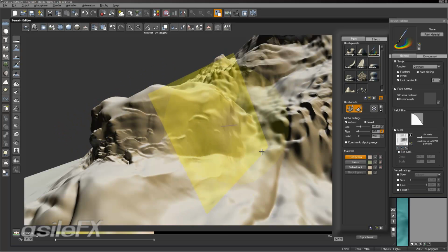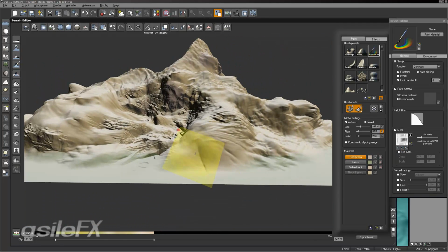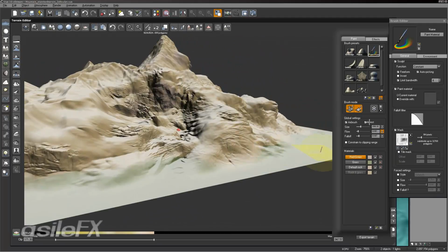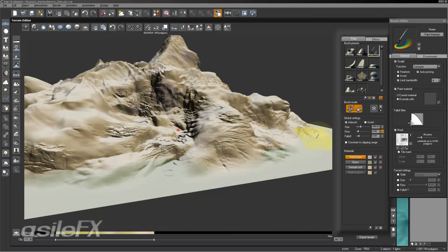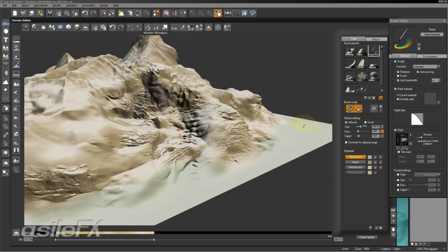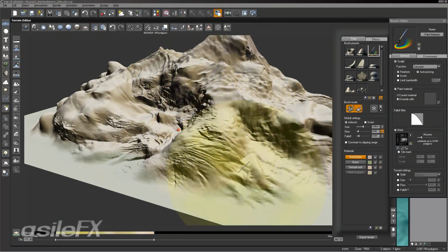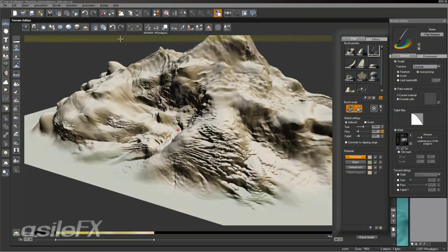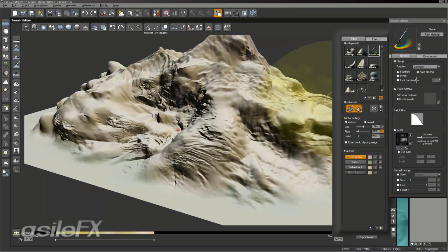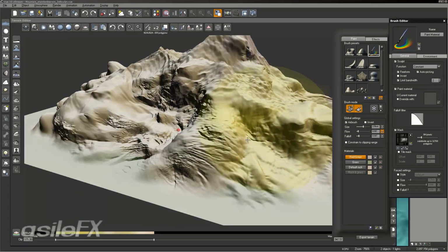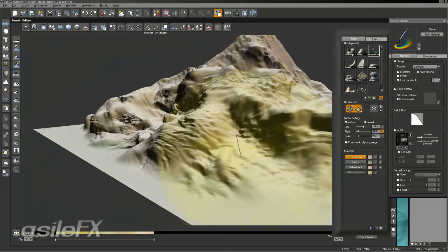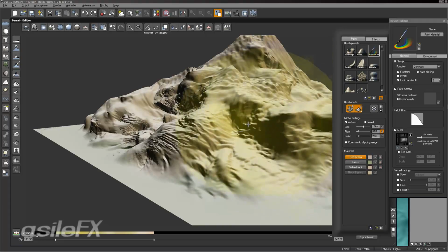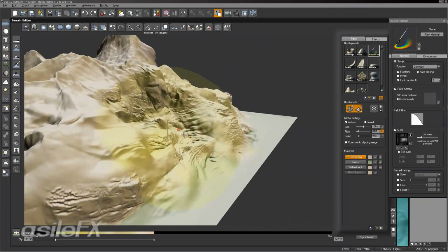We can rotate the texture map. And we'll turn off the inversions. Go back and kind of work on some of the other areas, maybe increase the size of the brush. If we do that, we probably will want to turn off the limit bandwidth. Oh, maybe not if it's creating too much detail. Just raise it to a bandwidth of 2. And that way we can affect larger areas.